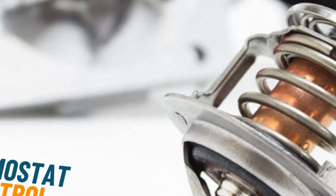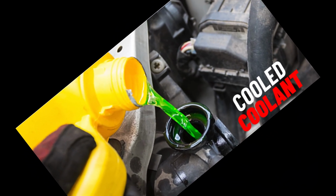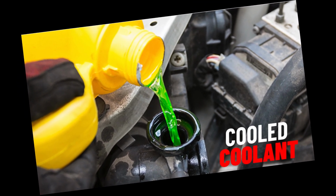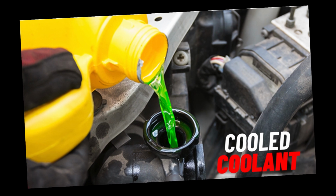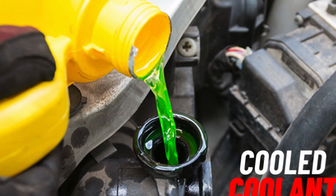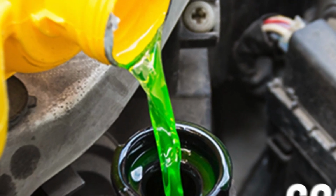The cooling cycle. Number 1. Coolant circulation. The cooling cycle begins with coolant circulating through the engine, absorbing heat generated by combustion and friction. The coolant absorbs this heat and carries it away from critical engine components. Number 2. Air cooling.